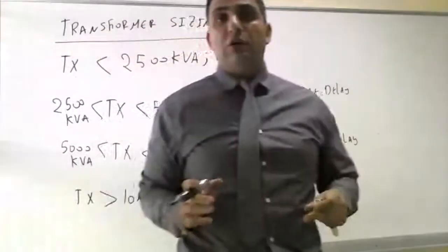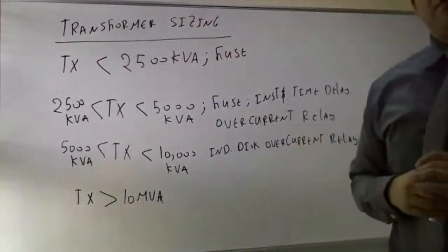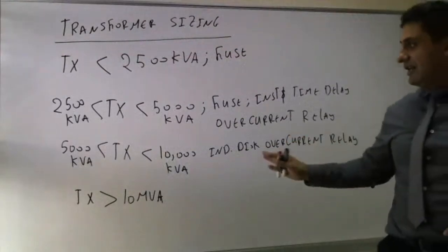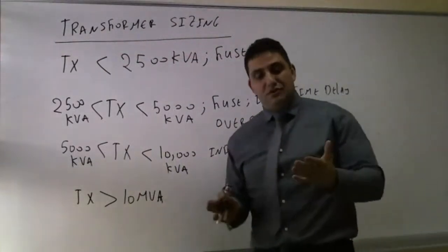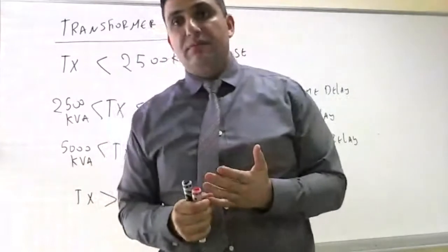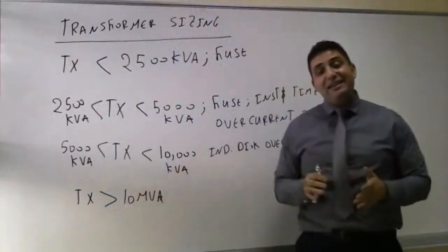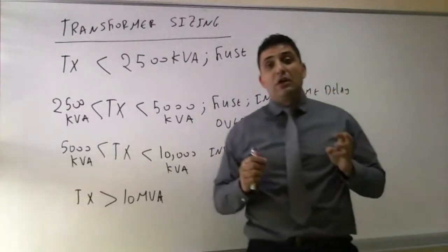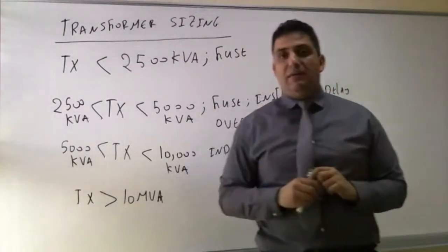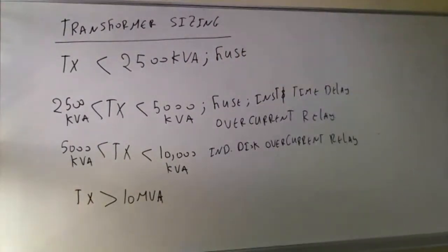this is now where we start going into a substantial amount of power. So under this condition, we have to use harmonic restraint to actually monitor from its harmonic relay. And at the same time, we have to use something called percentage differential relay. What are these two elements? These two elements will make the core of our calculations and our design when it comes to transformer protections.